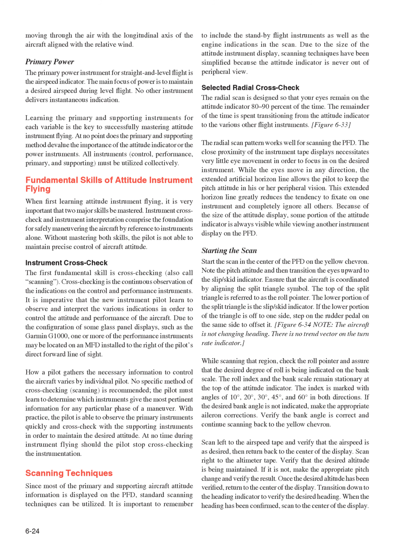At no time during instrument flying should the pilot stop crosschecking the instrumentation. Scanning techniques: since most of the primary and supporting aircraft attitude information is displayed on the PFD, standard scanning techniques can be utilized. It is important to remember to include the standby flight instruments as well as the engine indications in the scan. Due to the size of the attitude instrument display, scanning techniques have been simplified because the attitude indicator is never out of peripheral view.